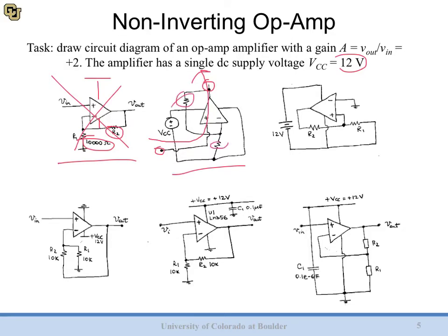None of our components have either designators or names or component values on them, so we don't like this. Additionally, we haven't labeled ground. There's a lot of problems with that. Try to avoid that completely.